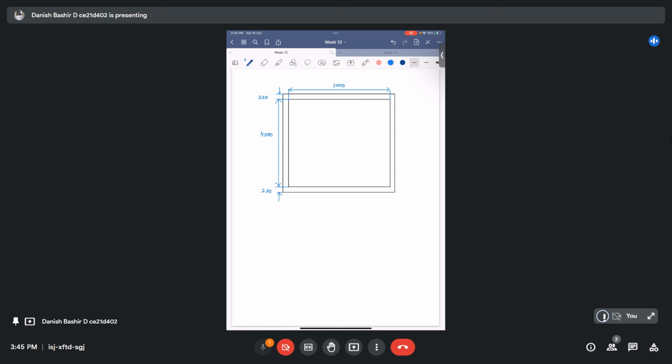So we have to provide the reinforcement like this one. I will make two color codings like this one: reinforcement like this, then bent, and then straight, alternate bent bars. Okay, same, another one will be like this up to this point.